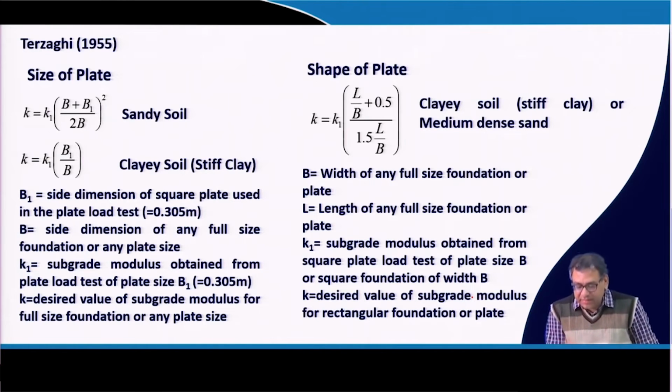So, remember that suppose you have done the test on a 30 centimeter plate, and you want to determine what would be the bearing capacity for a 1 meter by 2 meter foundation. So, first you convert 30 centimeter to 1 meter.